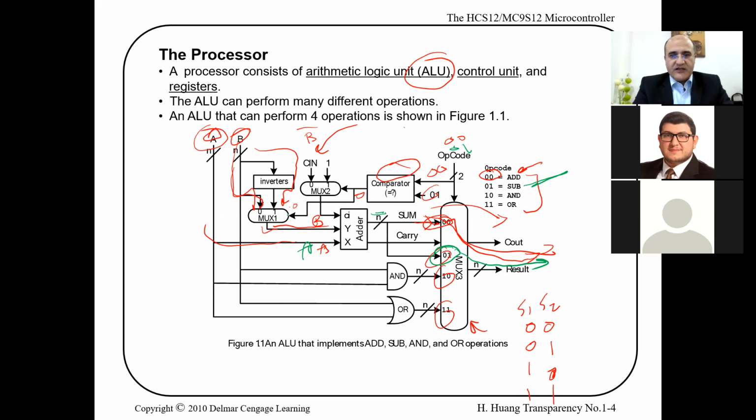This multiplexer has a select line coming in from the comparator. The comparator compares this time 0, 1 with 0, 1, right? 0, 1 matches 0, 1. Yes, you get a 1 here. The 1 is passed to this multiplexer, right? So the output of this multiplexer is this input, which is B inverted. B inverted is the 1's complement of B, okay? So here we get B complement.